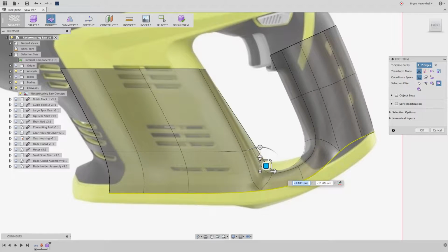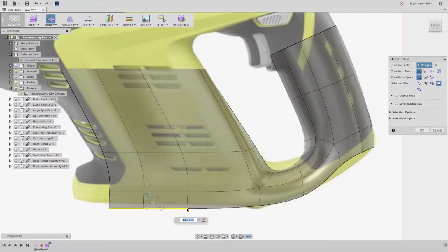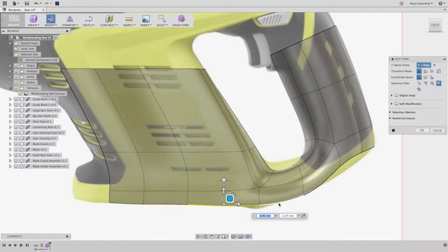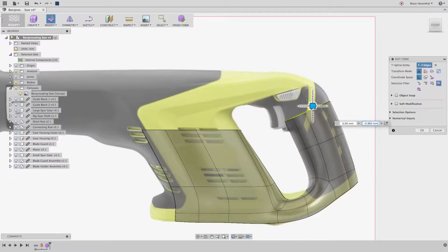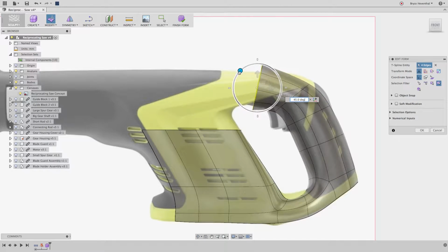Once the two bodies are merged, I can still manipulate this body just as before to get my desired results. In traditional CAD, I would be changing sketches, waiting for the CAD tool to solve the tricky loft or sweep, then hoping it didn't break any other feature. I will continue to use the same procedure on the top of this handle to get the desired transition. As the cylinder needs to navigate around this curve, I could rotate the edge loop to better match the curve.